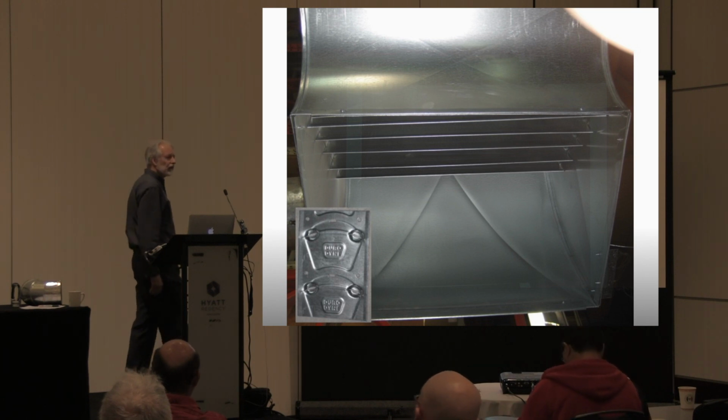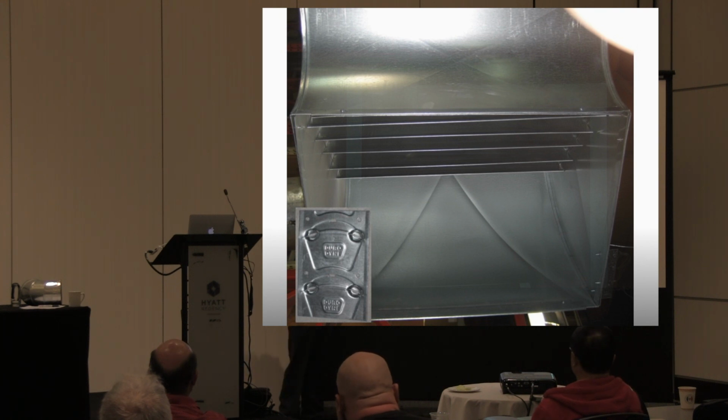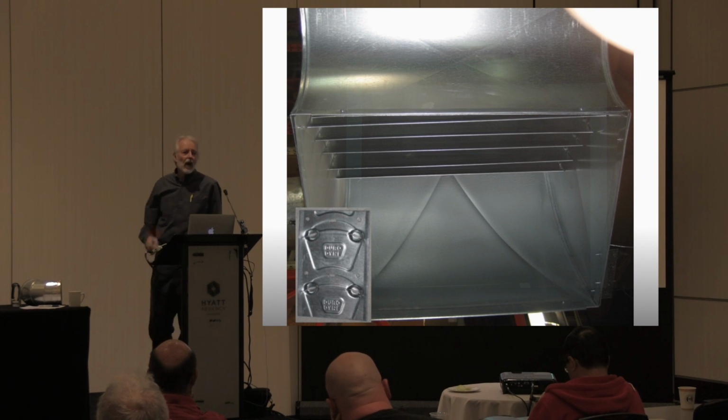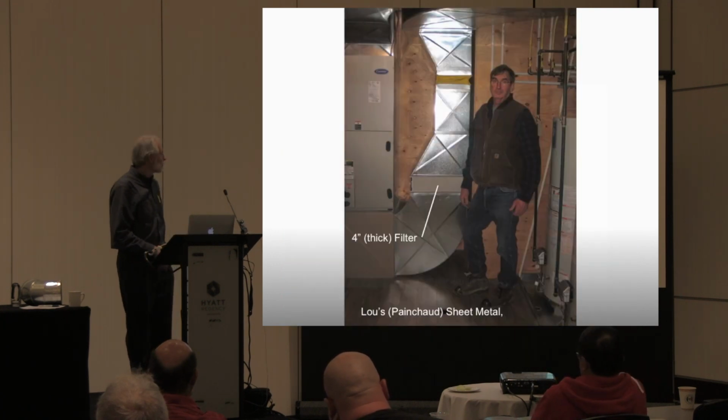That's what a turning vane looks like. You buy these things from Echo that sells Duradyne. Their rails are sold up in a coil, unrolled and flat. You roll these up, stick them in these little recurves, tap them into place, spot weld that in, and you just saved yourself 88% of the pressure drop, and you've hugely extended your filter life if you did it there.